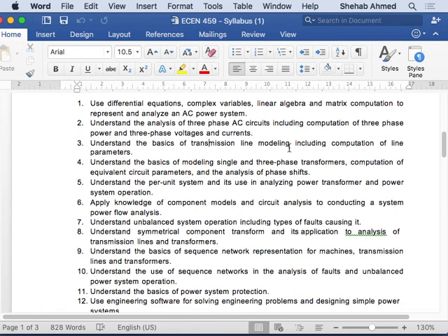The objective will always be to take the real device, find an equivalent circuit, and put it in the simple model that we have that will look exactly like what I drew, right? And then do the same thing with the transformer. Find its equivalent circuit and the parameters from the nameplate data of the real transformer, and plug it into the circuit.